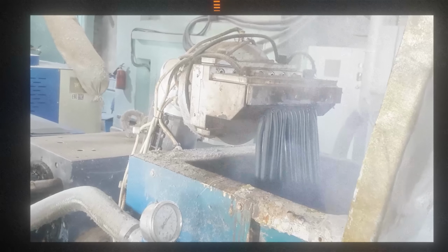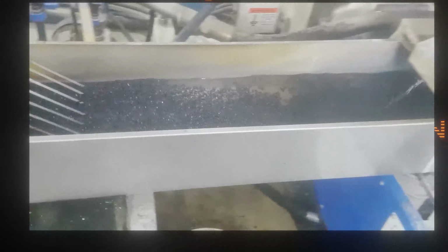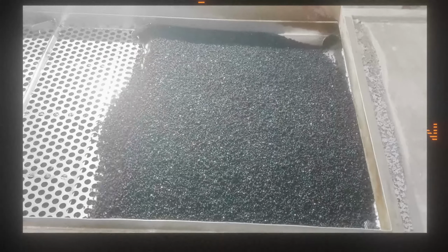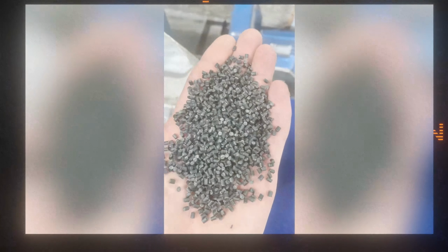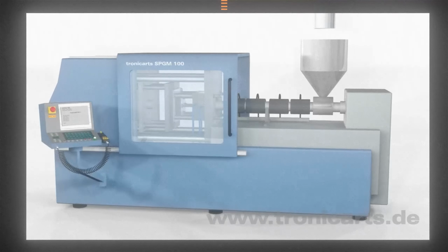3. Mixing. All components are evenly distributed throughout the polymer mass. 4. Cooling and granulation. The finished material is cooled and reformed into injection molding pellets, but now with an increased MFR, 10 to 50 grams per 10 minutes. These modified pellets are now suitable for injection molding.